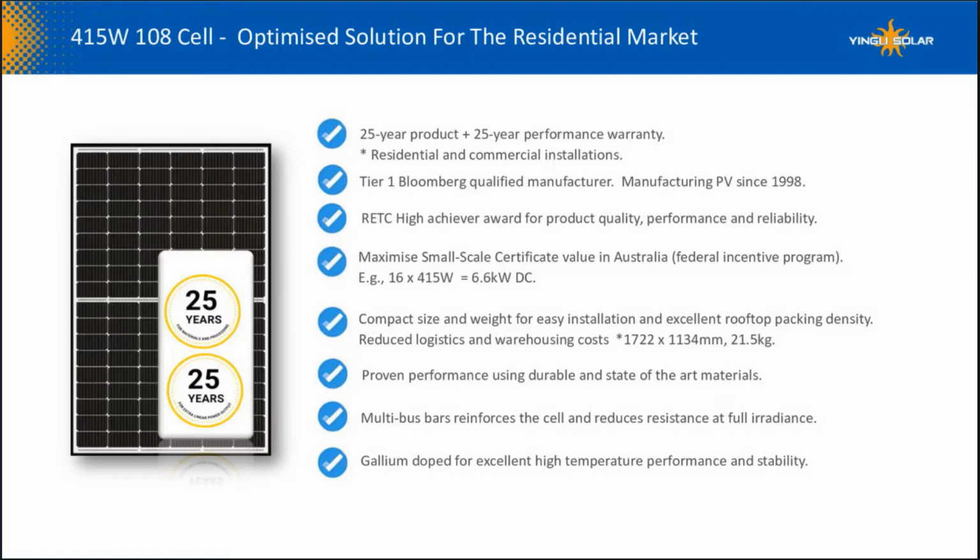It's backed by a strong Tier 1 manufacturer, Yingli, and has successfully passed third-party independent testing for quality, reliability, and performance. It also fits nicely into the very common system size here in Australia of 6.66 kilowatts. For our global viewers, the reason for this popularity is that it maximises the renewable energy certificates, known as STCs, where for a 5 kilowatt inverter, you can use a multiplier of 1.333 to establish the amount of panels that you can claim.